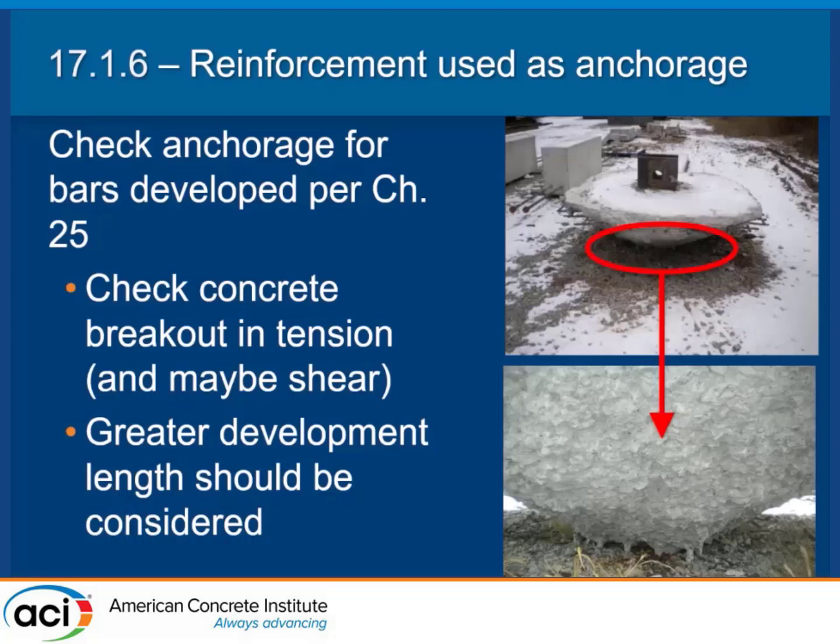Here we're talking a couple feet deep, and they didn't put any reinforcing steel for all intents and purposes. They just basically poured a lot of concrete. They put in some top bars and bottom bars, and this big old eyelet to take the stay wire, and said, okay, it's good.